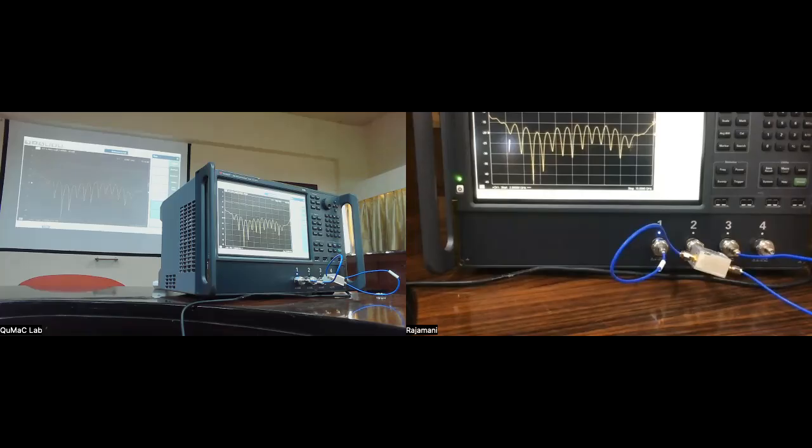This is because the actual functioning of this device in this reverse direction is that on this port, it gives you the sum of the voltages on port 1 and 2. And the difference of voltages of 1 and 2 gets dissipated inside this hidden resistor. Okay, this is something we will derive later on when we actually study this device in detail.